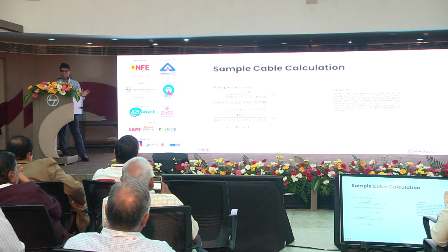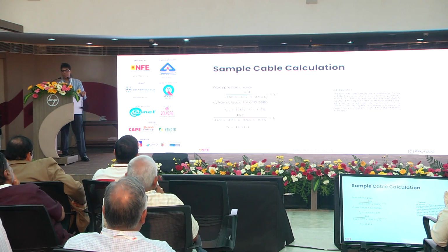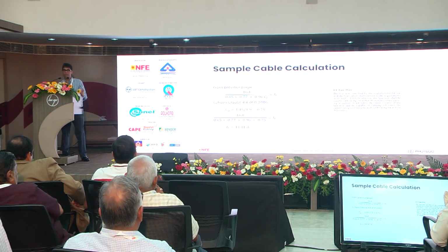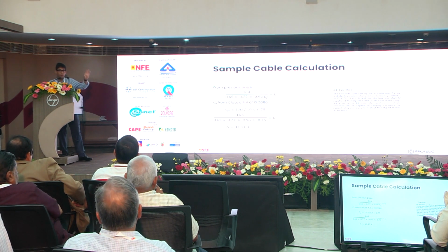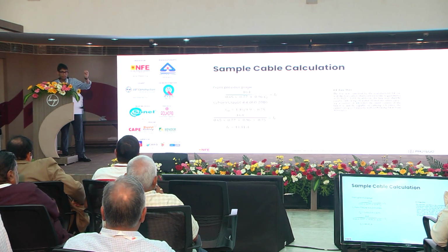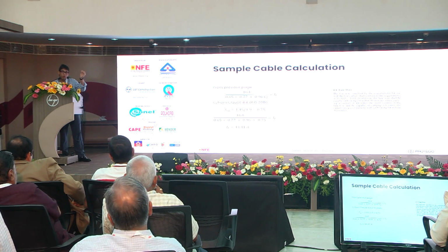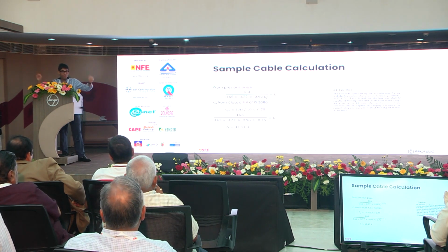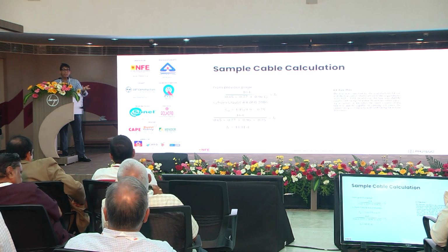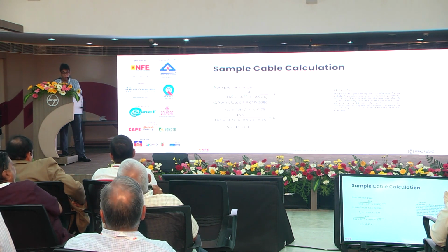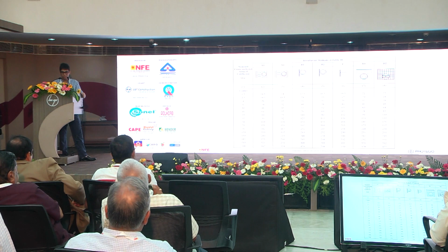So we plug in 0.75 and you get a cable that needs to carry more than 44.41 amps. So do you see how for a 16 amp protective device, a correctly sized cable as per the regulations has to carry 44.41 amps. Massive difference. You might say 16 amp cable, let's use 2.5 square millimeters. No, you need to consider all these factors.